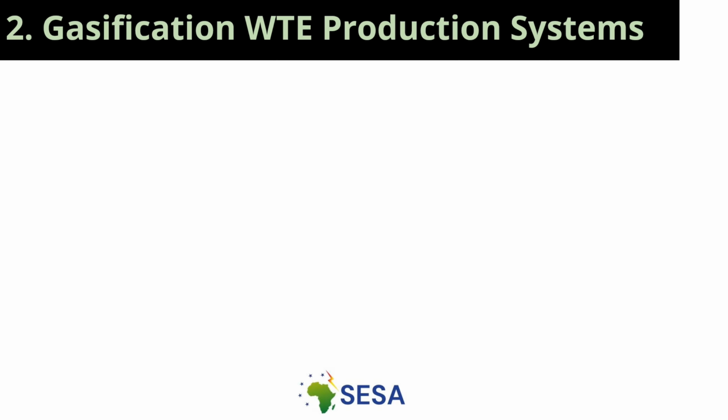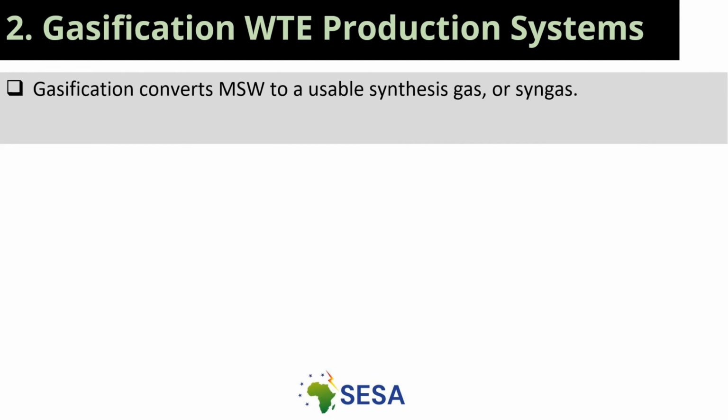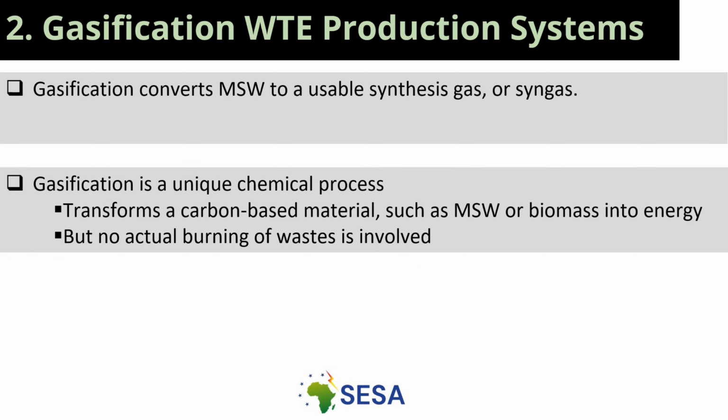Another waste into energy production system is gasification. It is a process that involves conversion of solid waste into gaseous combustible fuel through a sequence of thermochemical reactions. Various steps in gasification include upstream processing, gasification process in the gasifier, and finally downstream processing. Upstream processing involves size reduction of waste into appropriate sizes suitable for gasification. It further involves drying the waste to achieve appropriate moisture so that the process can work efficiently.